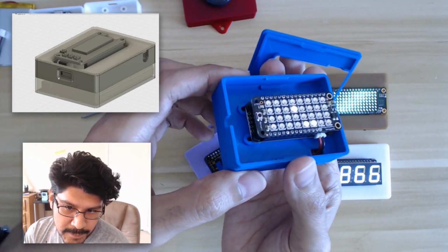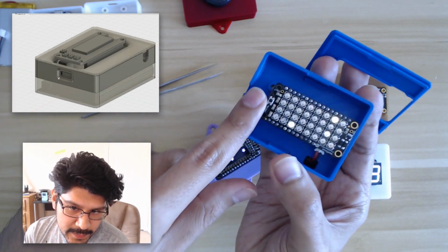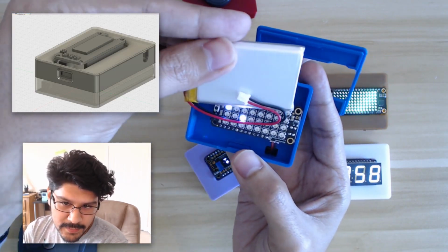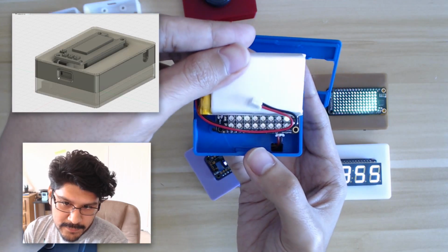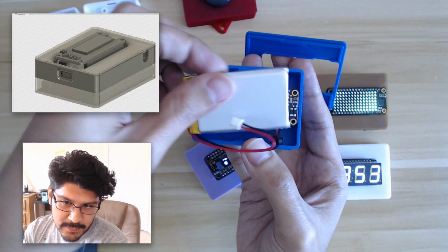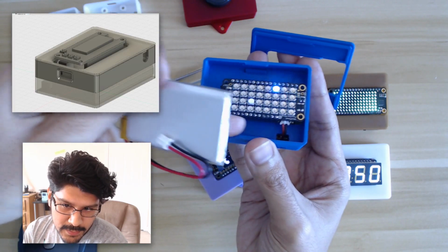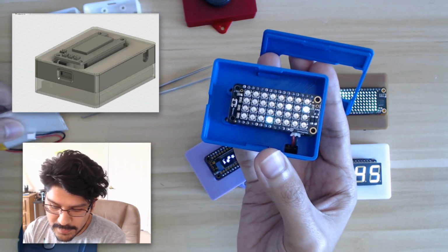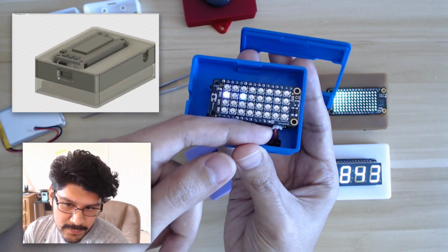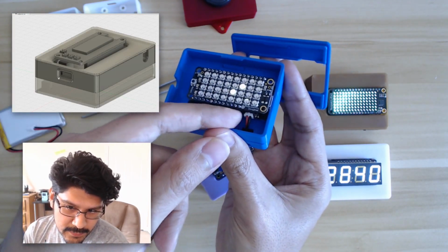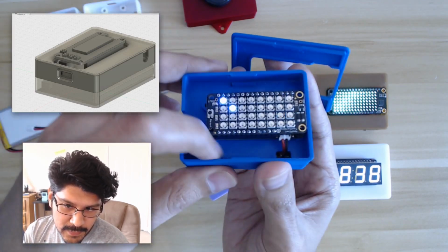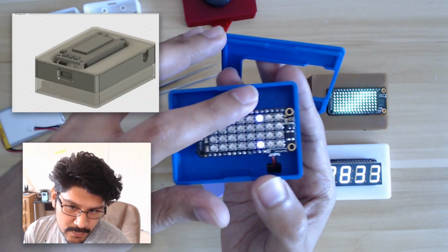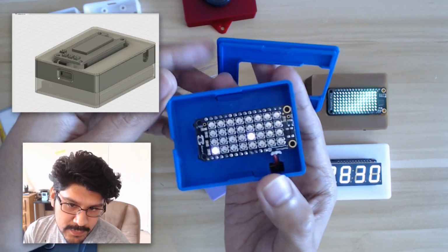So if you're wondering why there's a little bit of gap here and not a gap there, it's to accommodate the size of the battery. If you look at the battery here, that's about the size that you can get. There's a little bit of play here and here, and that's just so that you have the option to put something here, maybe another battery, a button or something, and of course to be able to remove the JST connector here from the battery compartment. So that's why there's a little bit of gap there. All this is parametric, so you have the option to increase this or decrease it however you want.